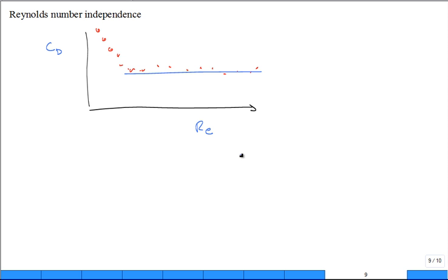It's that drag coefficient quoted as a single number for an automobile, because the automobile driving down the road is out in the turbulent regime, out in the Reynolds number independent regime, and it just quotes a single number. And that number could be something like 0.25.